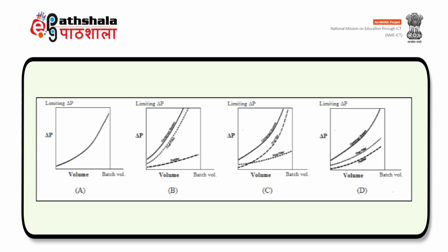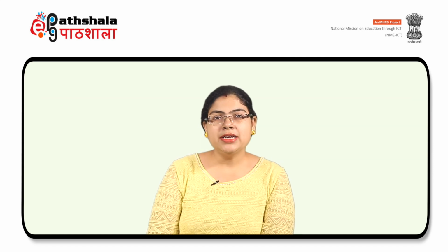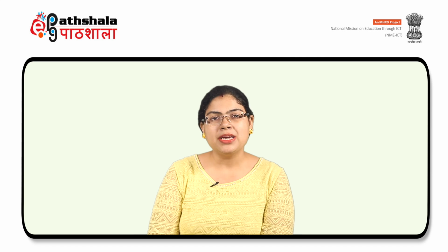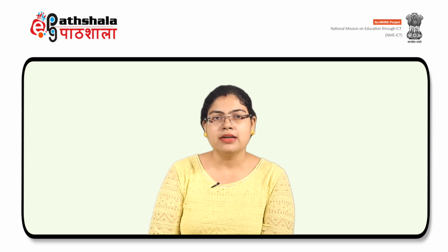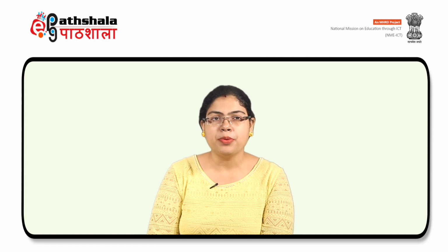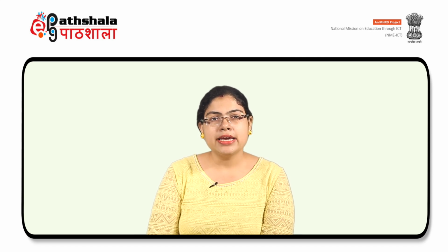A final filter that is not protected by a pre-filter has a short filter life. When a pre-filter is used in combination with a final filter, the efficiency of the pre-filter is maximum, and in these cases it is important that the O-ring seal sits directly on the membrane itself and not on the pre-filter. Therefore, the diameter of the pre-filter selected should be somewhat smaller than the diameter of the final filter. Seating the O-ring on the pre-filter often fails to produce a seal, thus causing the filtration system to leak. This leakage may result in the filtrate being exposed to contamination.